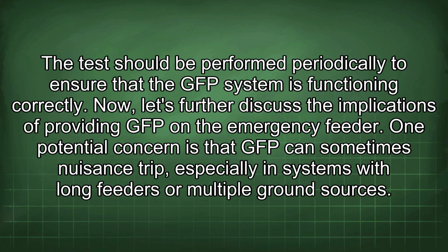The test should be performed periodically to ensure that the GFP system is functioning correctly. Now, let's further discuss the implications of providing GFP in the emergency feeder. One potential concern is that GFP can sometimes nuisance trip, especially in systems with long feeders or multiple ground sources.